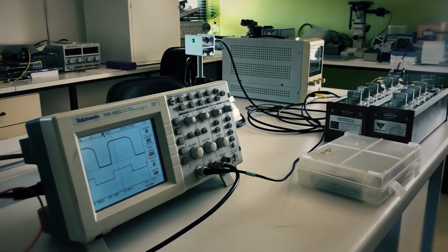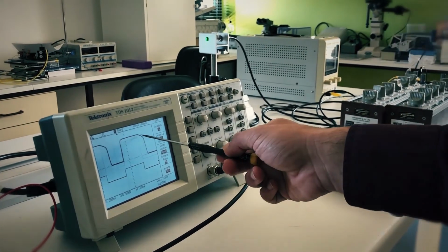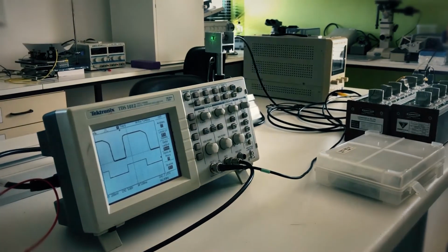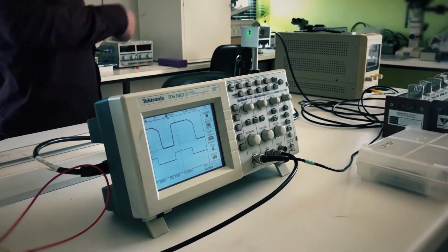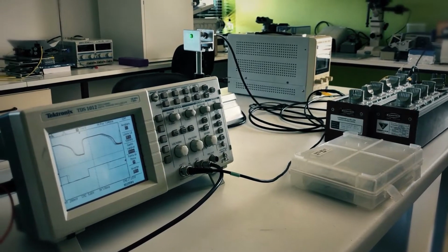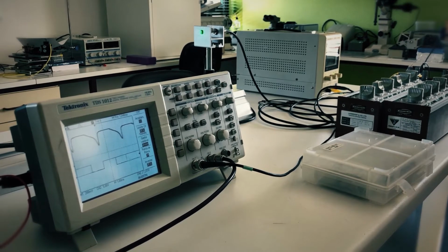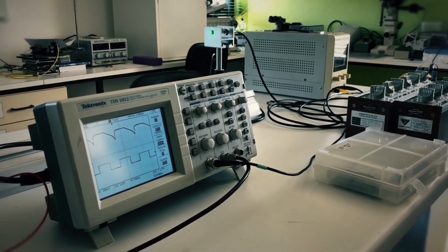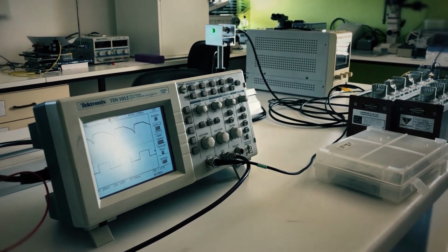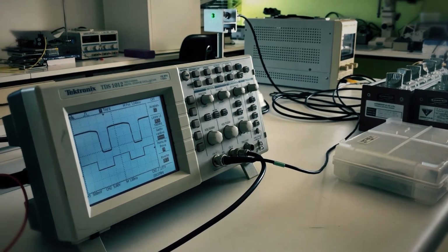So, why does this happen? When increasing the resistance, we are basically making it harder for the free carriers to travel across the device and reach its terminals. This mostly affects the slow carriers, which are responsible for the fall time increase. This effect is very critical because at high frequencies, the photodetector is not able to fully discharge, cutting significantly the current output. When the amplitude of the photodiode's response is cut by half of its maximum, we say that the device is cut off. And how do we fix this?